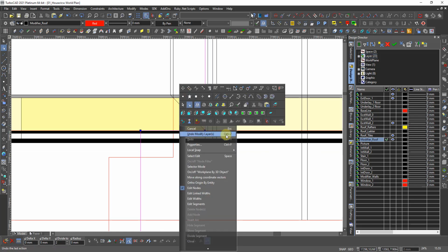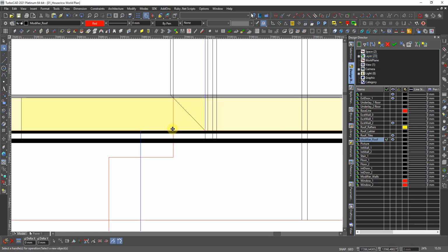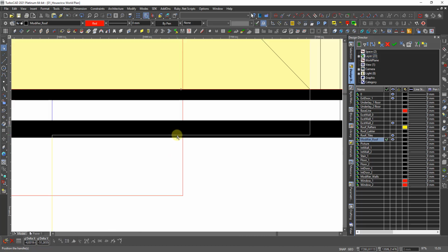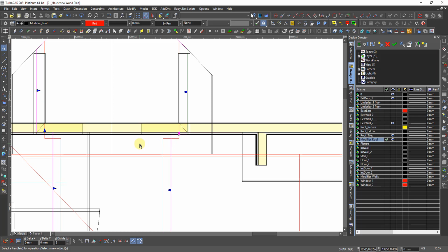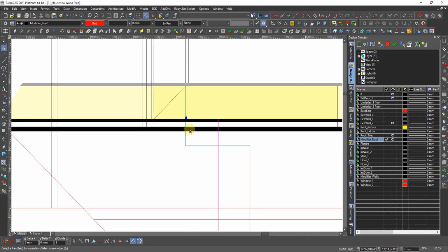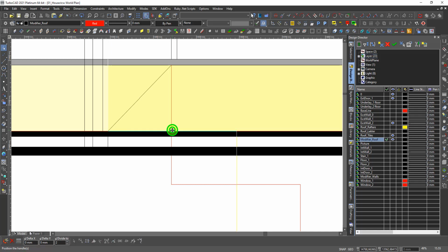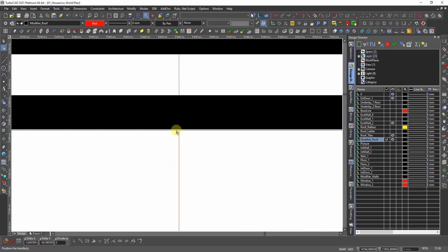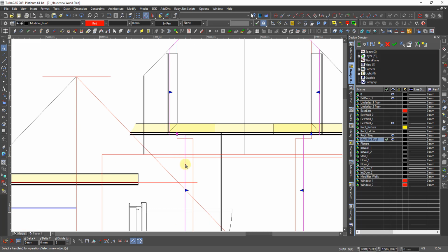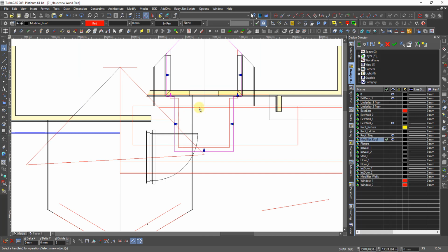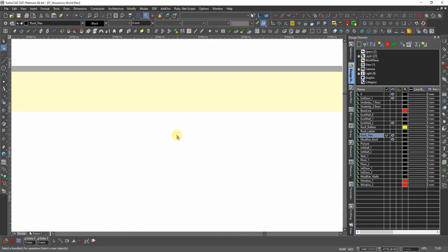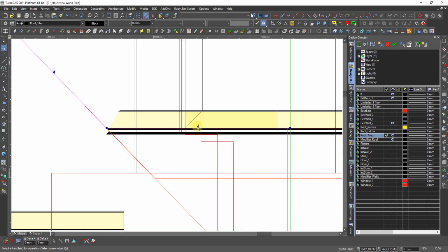I take the edit tool and I go to segment, and I take this going down to N, I say a little bit outside. It's more correct also because in real life we don't put this that close. So a little bit distance. Now it should show in hidden line. And the same with this roof. I also want that. Now I have to be aware of this function, not pivot.